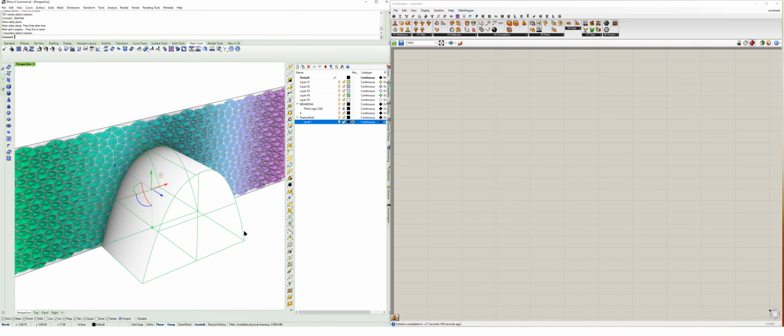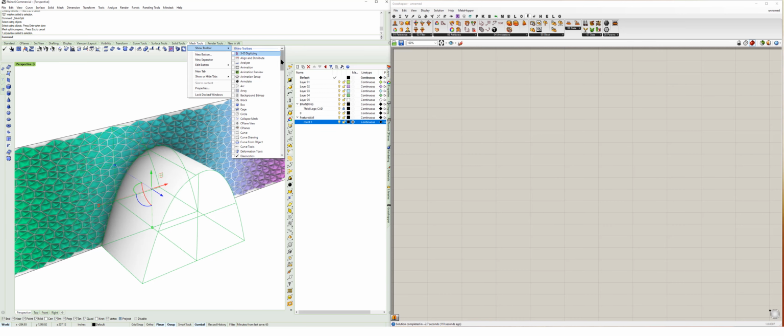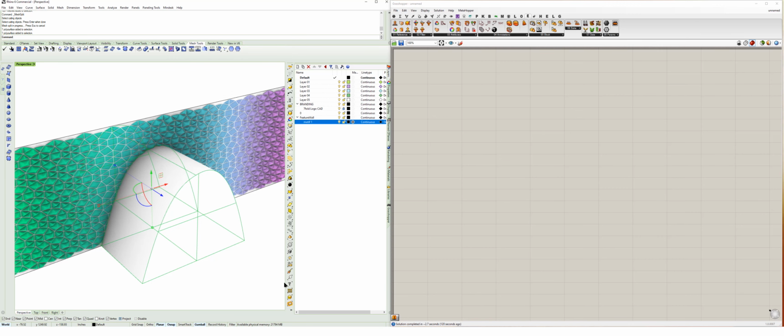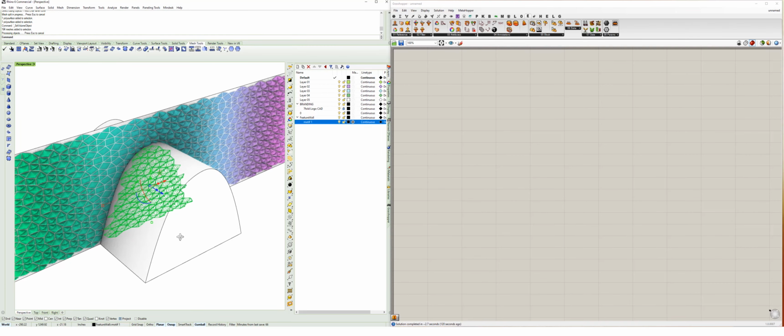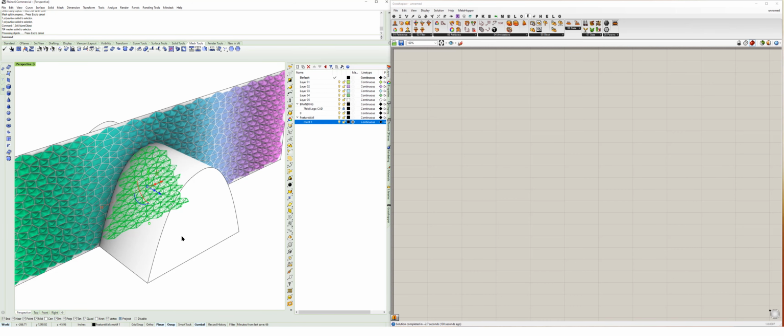Finally, I'm going to select my closed B-rep, go to my selection tab. If you don't have it docked here, there's a separate toolbar for select, which is right there. I have mine docked right on the side here. And selecting that, going down to select by closed B-rep volume, that gets me most of my geometry that just got cut. I'm going to delete that, and then I'm actually going to make this just a little bit bigger.